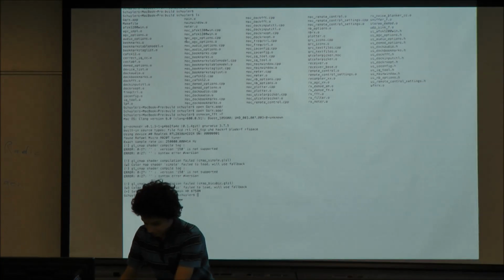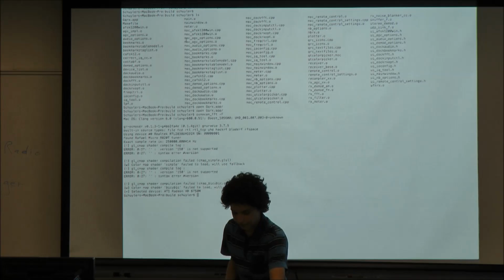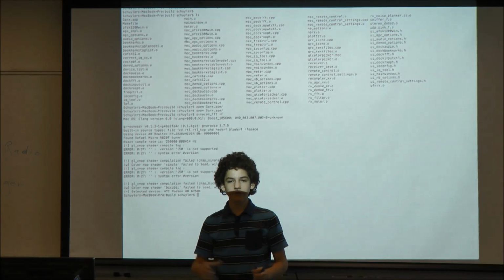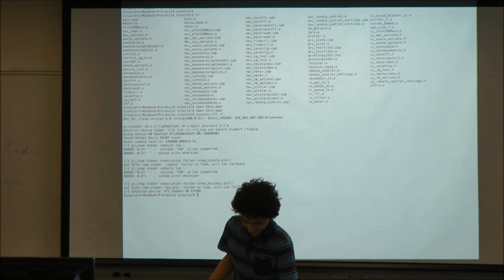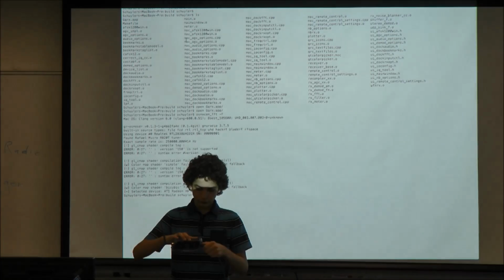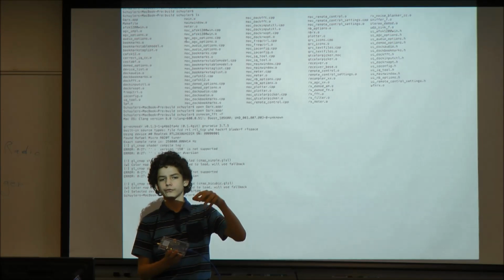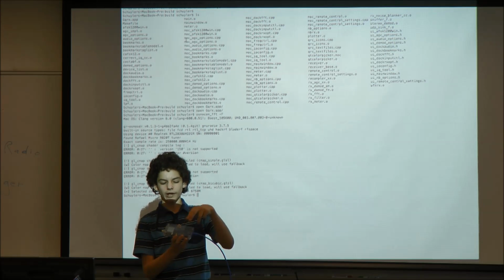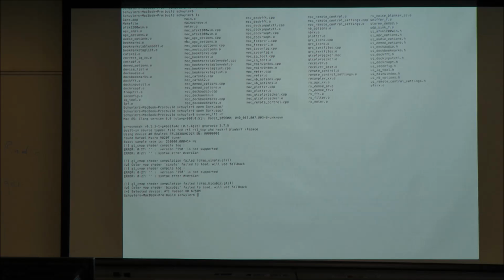But anyways, if I connect up the Blade RF, because it uses an FPGA, how many of you here have actually used an FPGA? You know how most of them you need a separate flash to store the data in? What the Blade RF does is you're connecting it to a computer. So instead of having a flash on here, you load the FPGA image when you connect it to your computer. You can set it up where it's stored in the flash for the firmware and the processor on here. There's an ARM processor on the Blade RF, and you could get that to do the same thing.